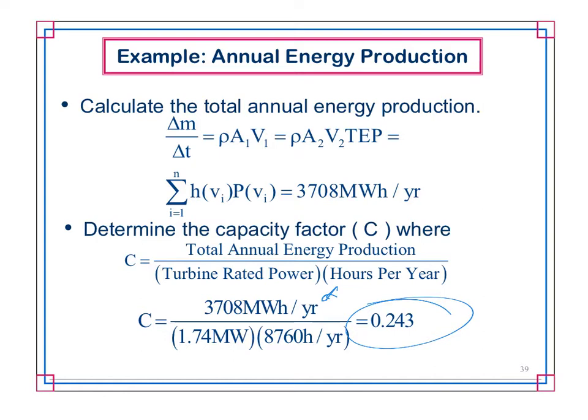And this is where fossil fuels, or anytime you have a system that has a fuel source, tends to have much, much higher capacity factors than renewable energies. So in the 10s or 20% for renewables, that's the best case you can do. PV is even worse, right? Because you might get peak sun 3-4 hours a day. So if you've got a 1 megawatt PV system that can do 1 megawatt, it can only do that for 2 hours a day. And that's assuming peak sun. What about if it's cloudy? So it really changes the equation quite a bit when you look at renewables. Where nuclear plants, right, we looked at nuclear plants, those are running at 90%.